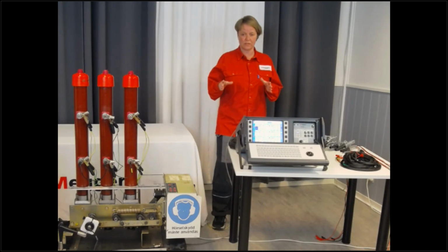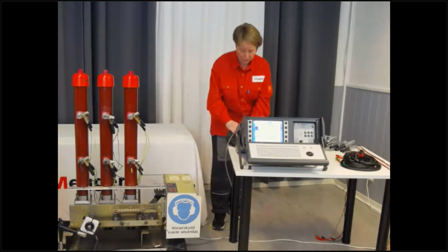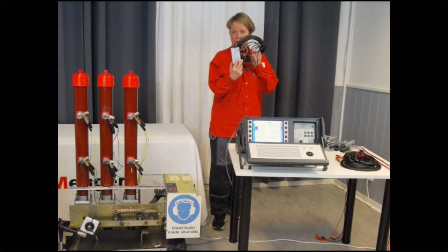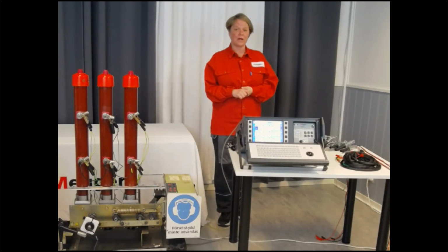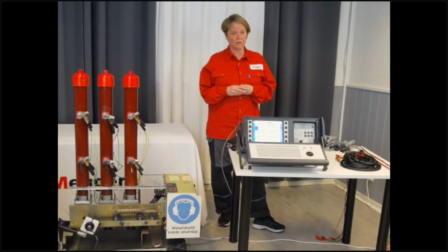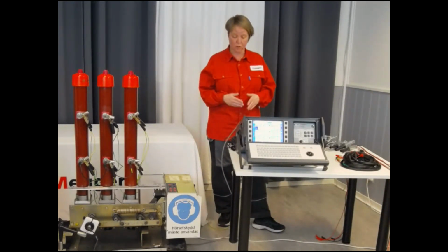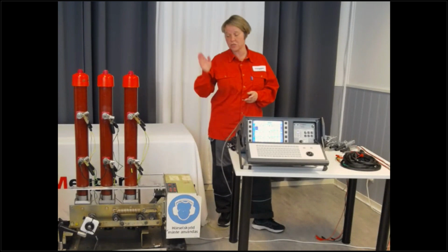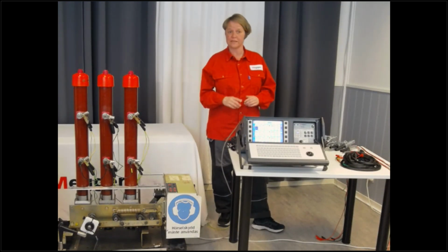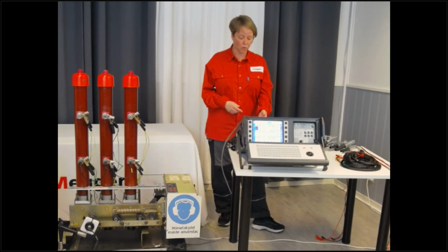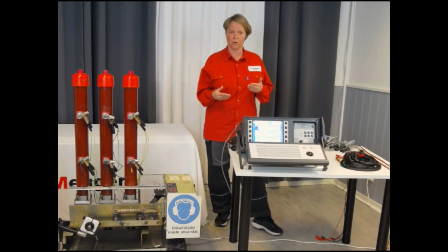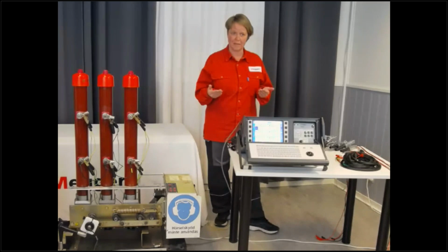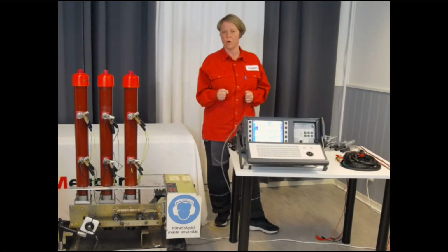But otherwise, when you do this, it's really, really easy to use. Instead of normal timing leads, use a box like this, and the whole measurement is done with resonance frequency instead of what we did with Eagle before, just a voltage and checking if there is a connection or not. So for the user, it's quite the same, especially on the outdoor breakers. It's as simple as a normal measurement, and of course much, much safer. That's what we developed this for. We wanted to be able to follow the regulations where it says you should keep the two sides grounded to work on the object.